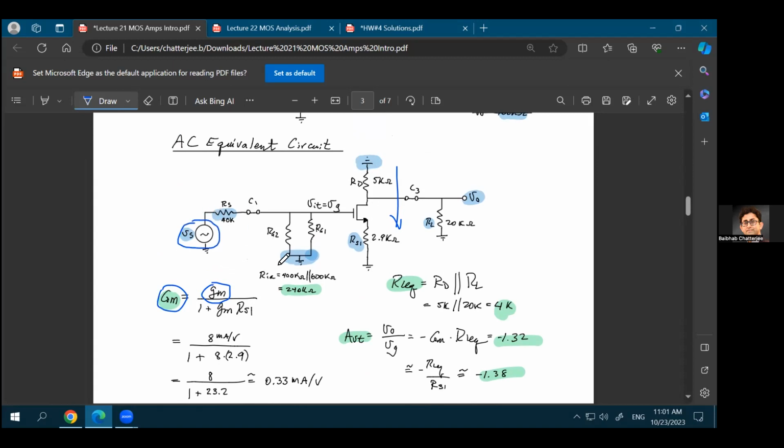On the other hand, the small gm says what is the change in the output current going through the MOSFET, between drain and source, as you are changing the VG voltage over here, or the gate to source voltage of this MOSFET. So that's what the small gm, or lowercase gm, tells you: what is the transconductance of this device. The uppercase GM is the transconductance of the entire system, where you have multiple resistances, capacitances, and all other things.